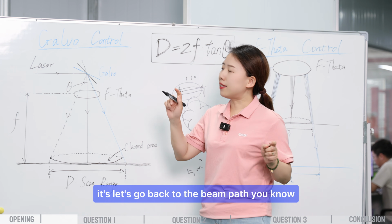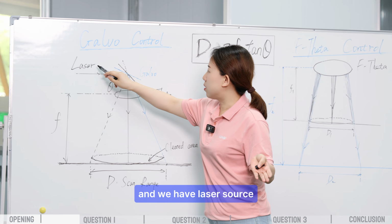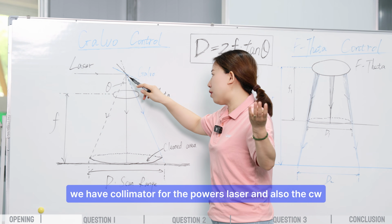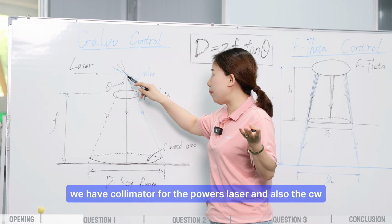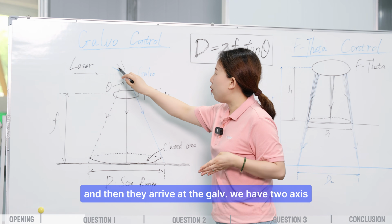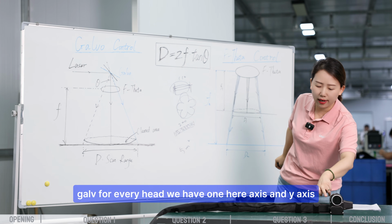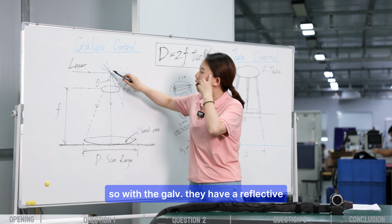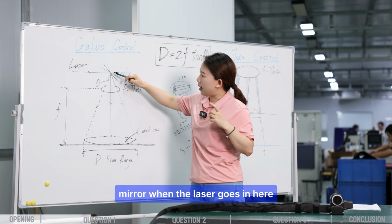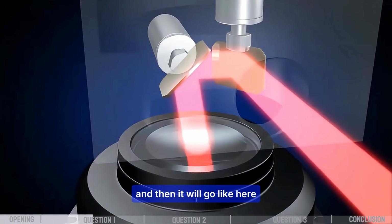Let's go back to the beam path. We have a laser cleaner and we have a laser source, which gives the laser beam here. And of course we have a collimator for the pulse laser and also the CW. Then after collimating, all the laser being collimated arrives at the galvo. We have a 2-axis galvo, for every head we have one, x-axis and y-axis. The galvo has a reflective mirror, so when the laser goes in here, it will be reflected here. So when you rotate, it will go like here.